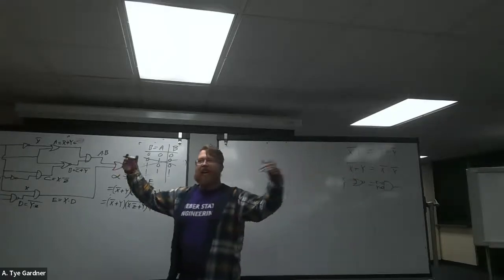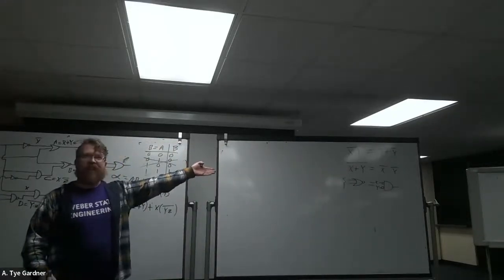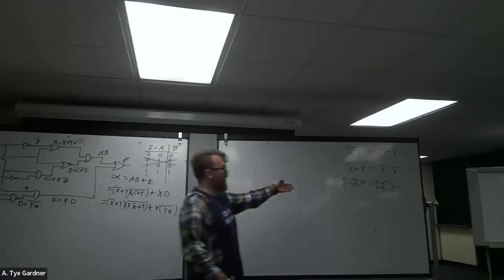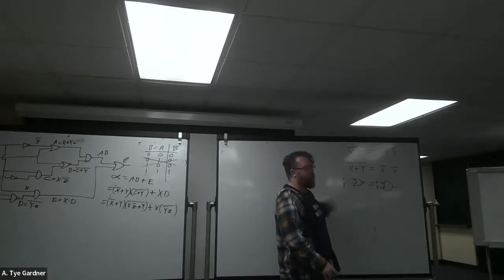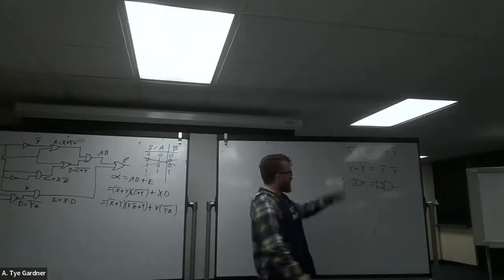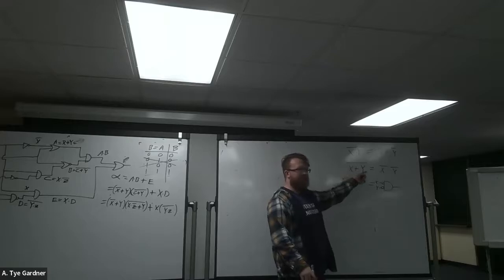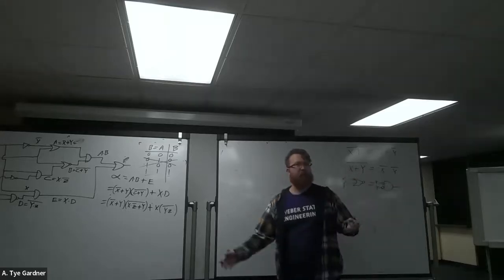Is that it's a Boolean expression of that gate equivalency. Right? I've just drawn what these gates are doing. So this is all De Morgan's is saying, which is anytime I have a bar over 2 terms, I flip the gates, invert the terms. Okay, that's all De Morgan says.